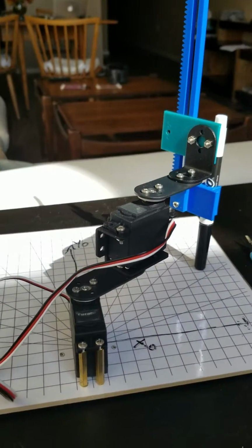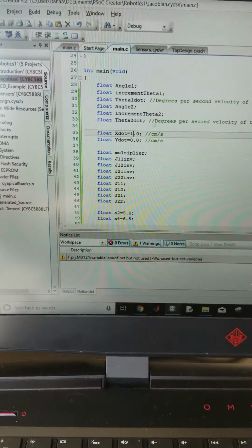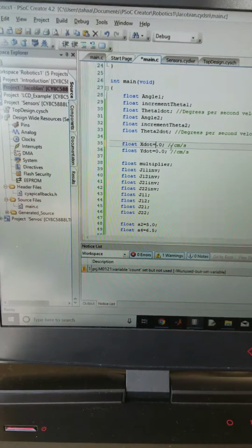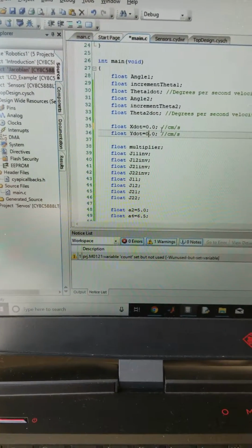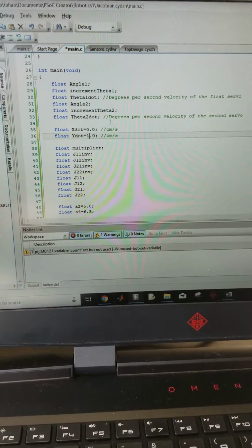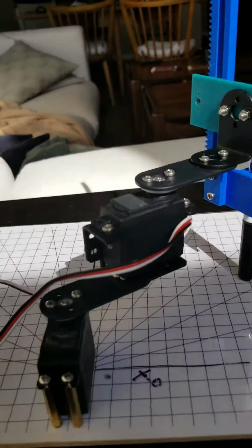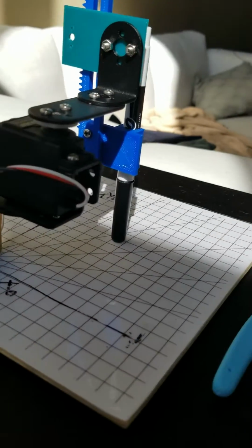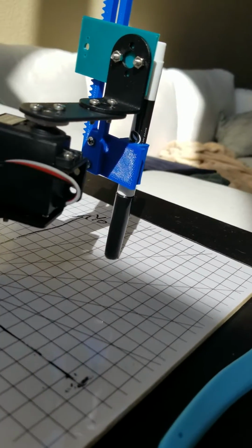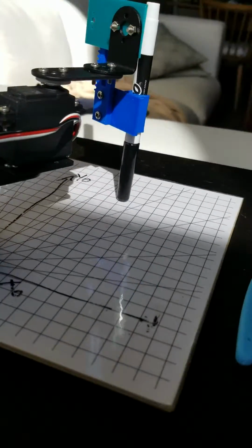I'm going to do the same thing, but this time with the y0 axis. I have the x dot value at 1 because I feel like the slower it moves, the easier it is to see. I'm going to change the y value to 1 for the same reason. So I will load this program. We'll take a look at my manipulator. So now we'll see it travel parallel to the y0 axis, just like the other one.